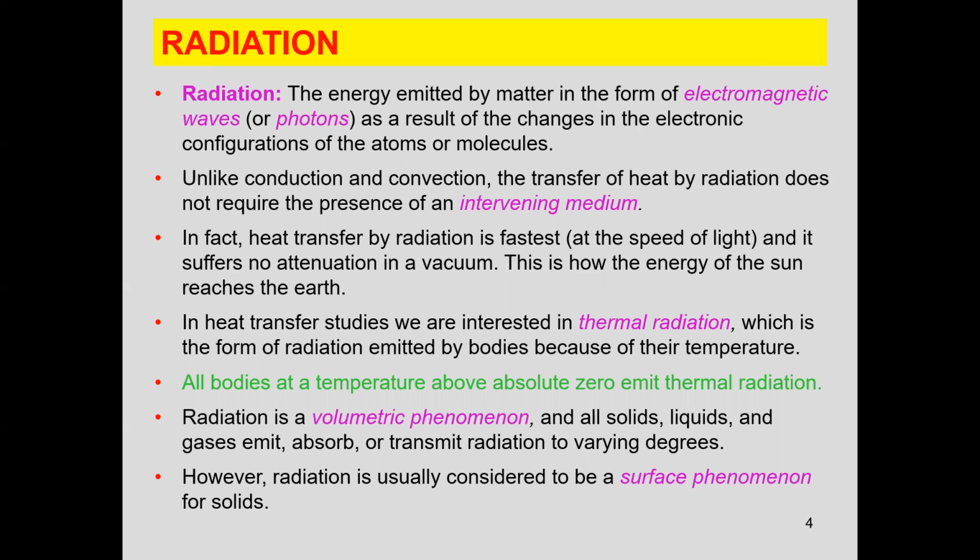In heat transfer studies, we are interested in thermal radiation, which is the form of radiation emitted by bodies because of their temperature. All bodies at a temperature above absolute zero emit thermal radiation. Radiation is a volumetric phenomenon, and all solids, liquids, and gases emit, absorb, and transmit radiation to varying degrees. However, radiation is usually considered to be a surface phenomenon for solids.